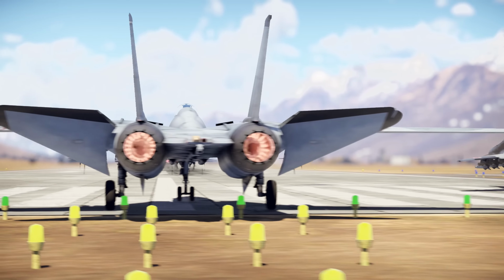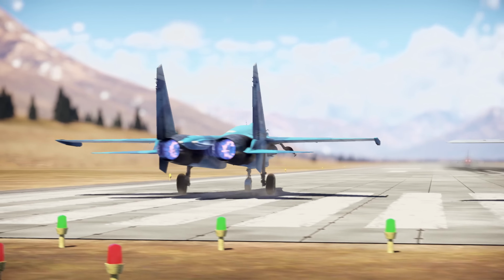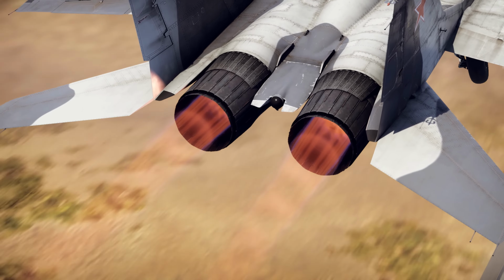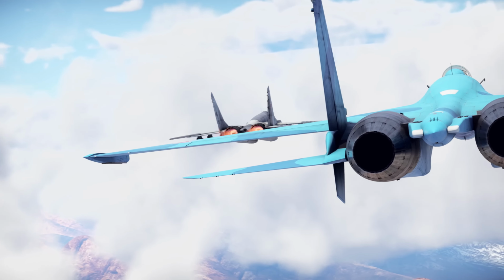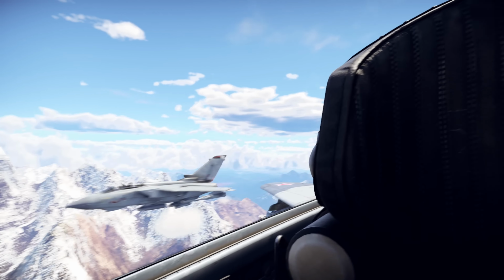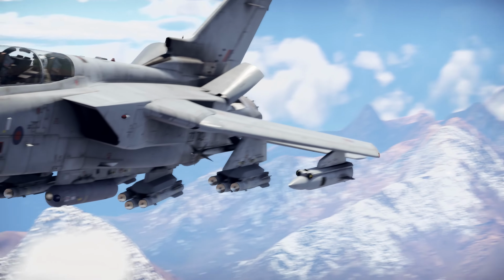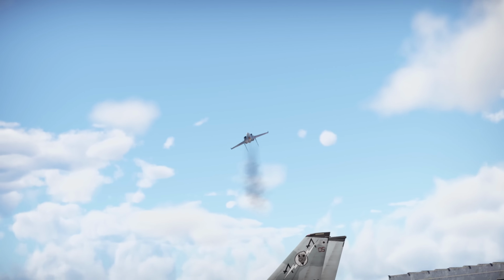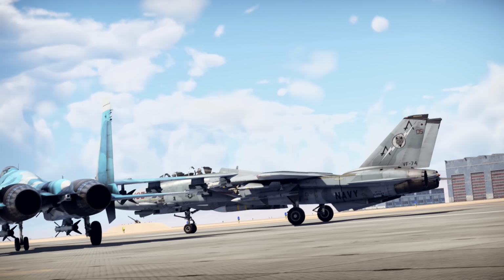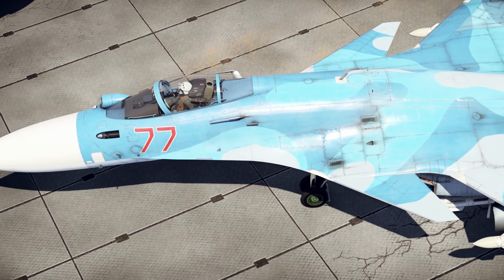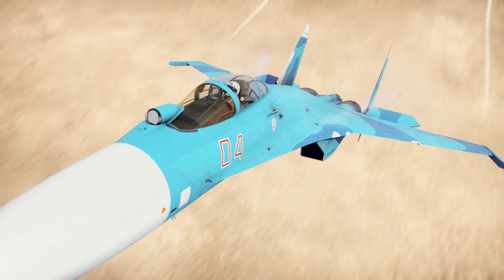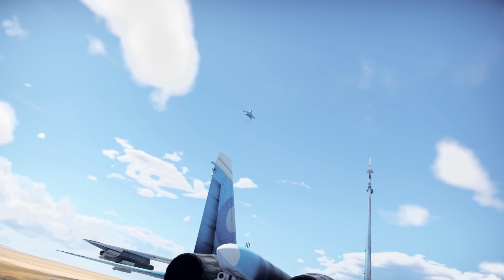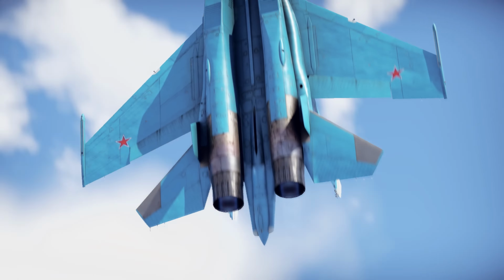Afterburners can increase thrust by as much as 70%, but at a cost of extreme fuel consumption and noise. This makes them impractical for airliners, but essential for military jets, since only afterburning engines can provide the acceleration and speed that modern fighters require. It's also important to note that these two thrust-boosting approaches aren't mutually exclusive. Most modern fighter engines are low-bypass turbofans with afterburners. Their bypass ratios are usually small, often less than 1.